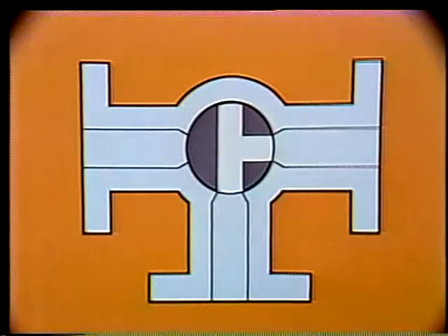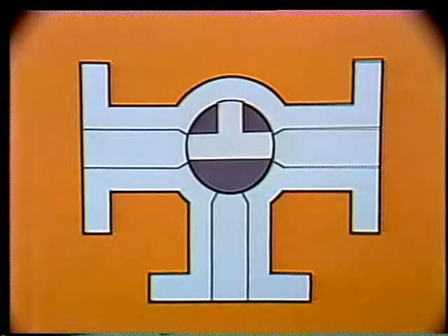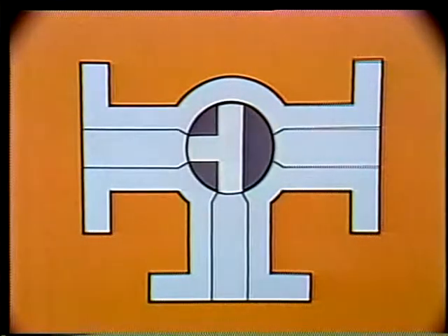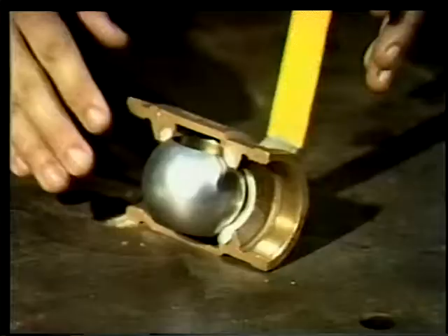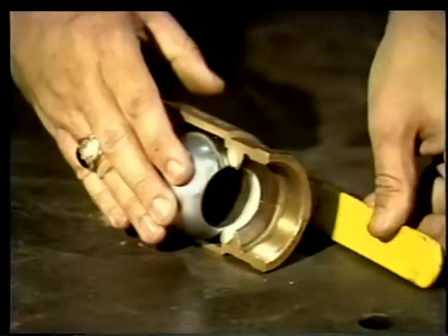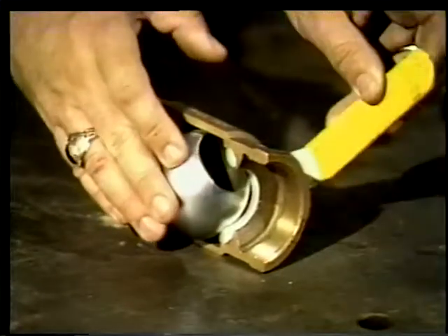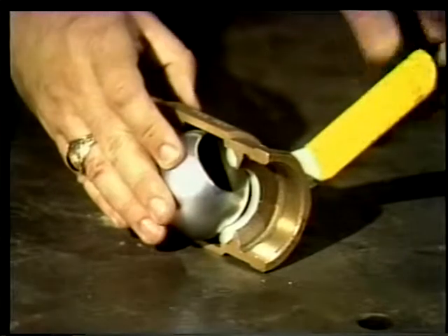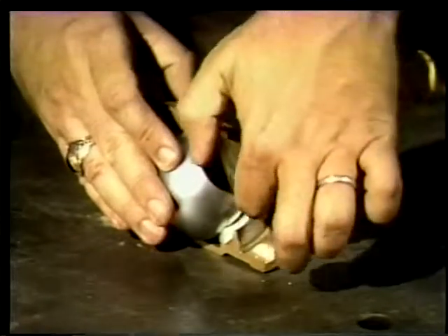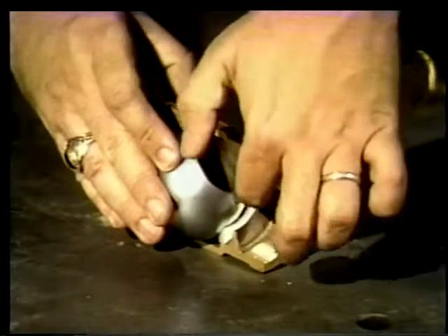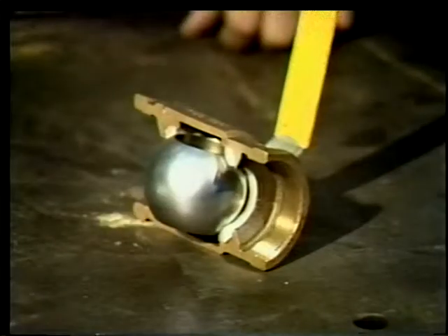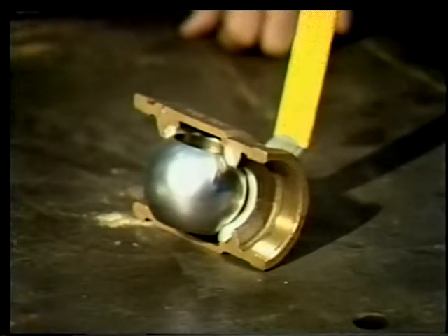Here is a three-way, three-port plug valve. There are three different flow paths available for the flow of a fluid. But if the valve is not lined up to allow full flow, a throttling action will take place. It's not good to let that happen, though, because the fluid will put pressure on the seals around the disc as it is throttled. The seals can be damaged by this pressure, and repair work would be needed.